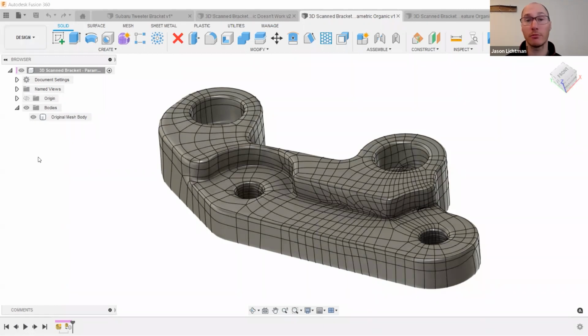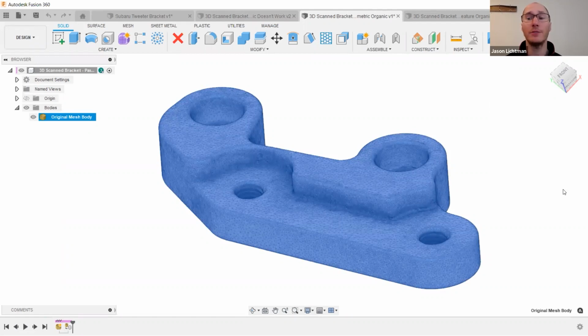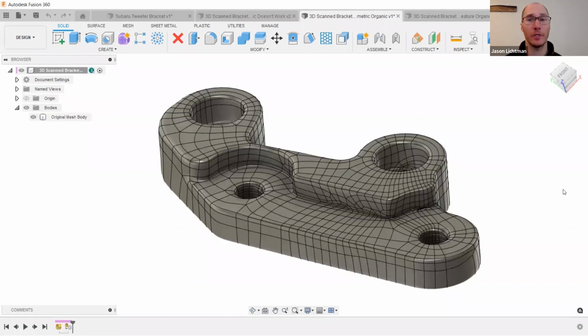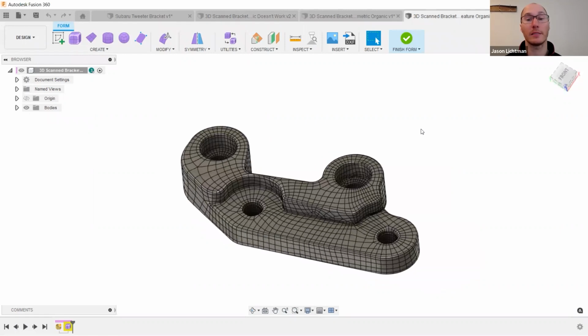A method that works really well for me. As I mentioned, when you're in this conversion dialog box, there is an option at the top to choose between parametric or base feature. Base feature is a non-parametric feature. It is a one-time conversion. If you wanted to change your settings, you would simply do that task again. And that's fine. Remember that the base feature method is going to do 2/3 of the work and stop.